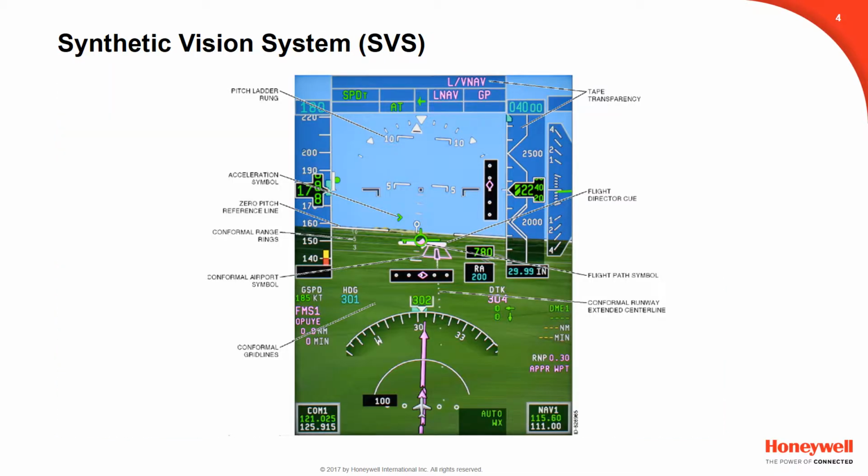The Synthetic Vision System, or SVS, enhances flight crew awareness by providing a synthetic, three-dimensional view of the surrounding environment, including sky, land, water, grid lines, obstacles, airports, and runways, in addition to standard flight and navigation data. The SVS uses obstacle and terrain databases to integrate existing flight deck data, field of view, and advanced symbology elements to assist in the pilot's ability to identify potential terrain and obstacle conflicts, as well as to identify visual references. Synthetic vision helps to reduce workload during certain tasks due to the increased amount of information presented to the pilot in a very intuitive way.